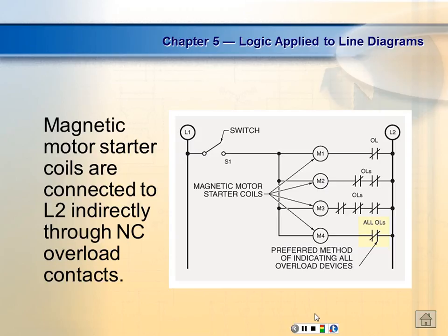So as long as we don't have an overload on our motor, these contacts are going to connect L2 to the load. If an overload exists, that means the motor, if it's running, it's going to click that line out, right? It's going to remove power from the coil. And then normally these overloads are not auto reset. These external overloads, they do not auto reset. You're going to have to push a button on them to reset. So if I don't...